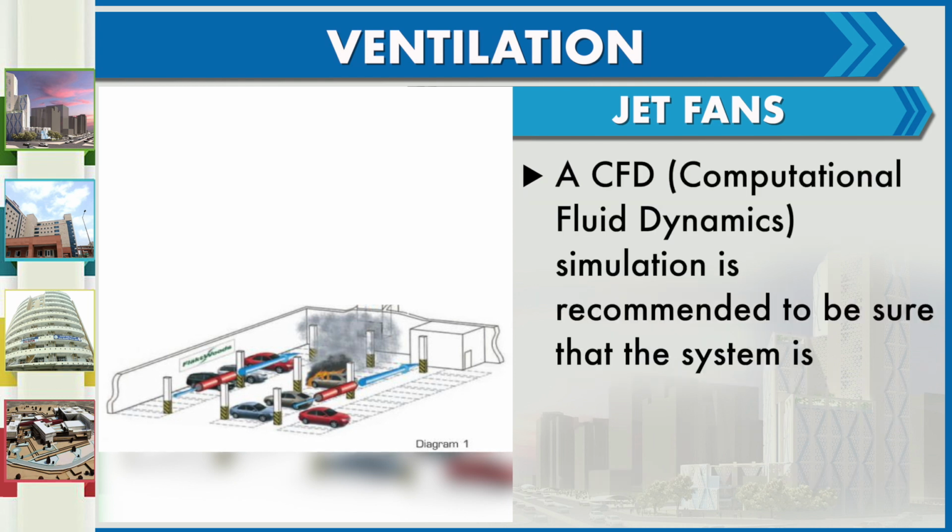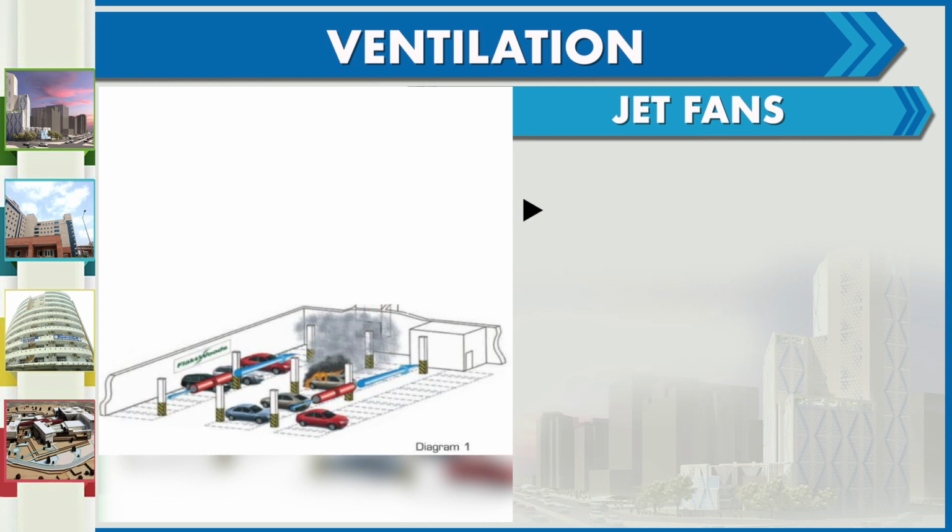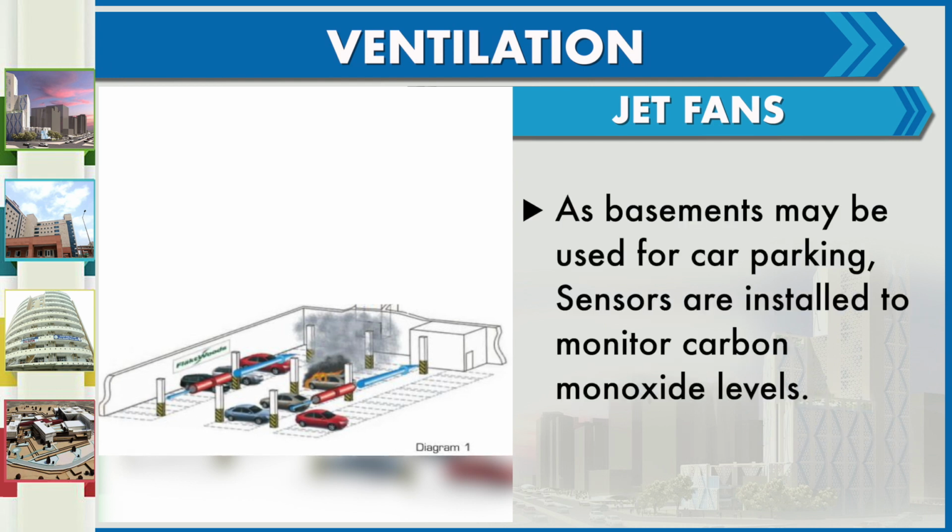A CFD, which is a computational fluid dynamics simulation, is recommended to be very sure that the system is correctly designed to extract all smoke during a fire. As basements may be used for car parking, sensors are installed to monitor carbon monoxide levels.